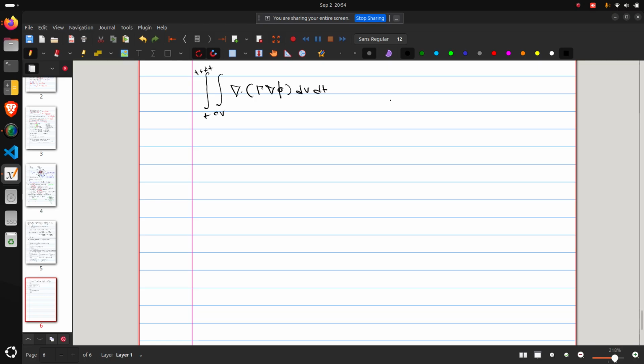Okay, so now we apply the Gauss divergence theorem as we have done for a long time, and make it discrete, that is a summation over all the faces. Summation of Γ∇φ times the area of the face, A_f. So this is at face f, right?